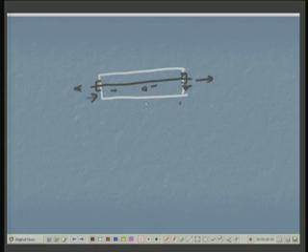So, the concrete is initially under compression. Then, when we apply tension to the concrete structure and snap off these wires, I have a composite section where the pre-stressing wire has been pulled, and through its anchor the concrete is being compressed, so it is under pre-compression.